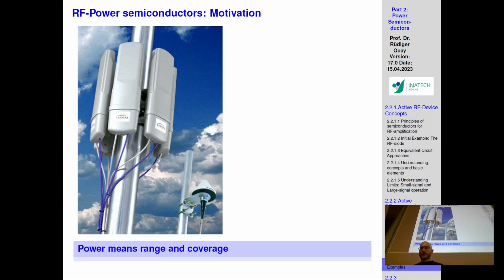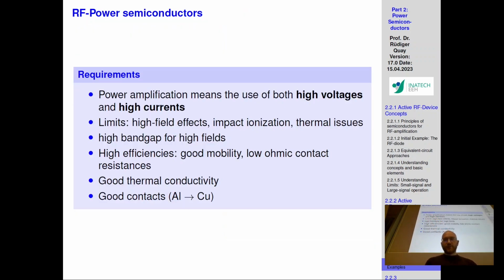And in this case, antenna design and power amplifier design come with each other. Power amplifier design, high voltages and high currents. As we said, we will apply high voltage. High currents will flow through there in order to have a high output power. We mentioned that there's limitations in that we have high electric fields across the drain gate contact, and those high electric fields can have a pinch off at some point, can generate heat.